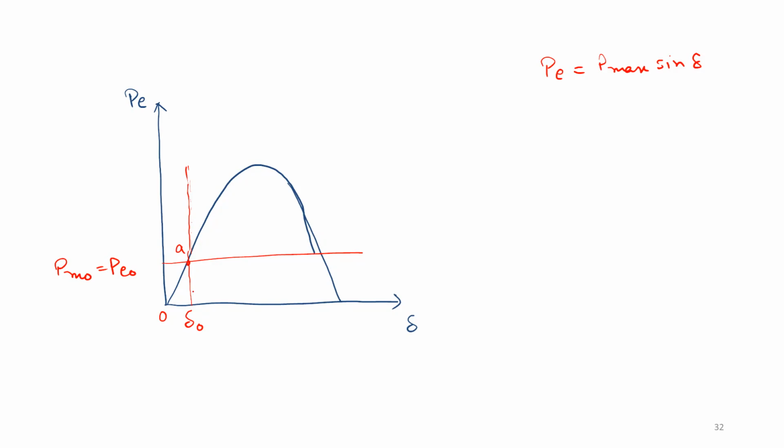So can I say your operating point will come, let's say this is B? Can I say that? Yes, sir. Okay. So initially my operating point was at A. That was before fault. During the fault, we just saw that the power transmitted to the infinite bus will be 0. So we see that the 0 line is along the horizontal line. So we can say that my operating point will come towards B.